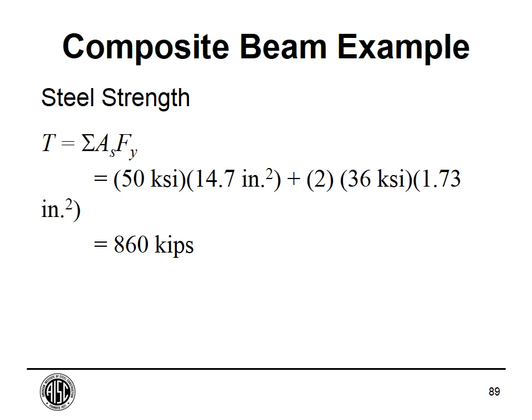Well, the answer to the first part is yes, because we don't need strain compatibility in a plastic design of the cross section. We really don't have strain compatibility between the concrete and the beam either. But we just assume that the load at a certain point and calculate it based on the plastic properties.